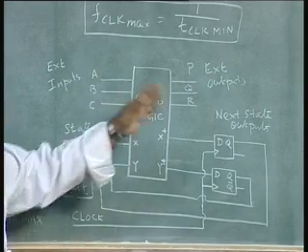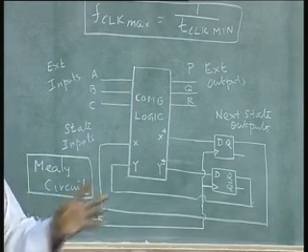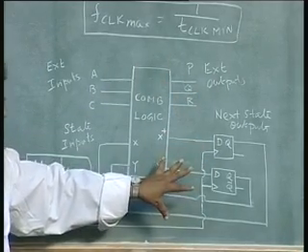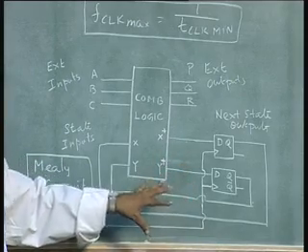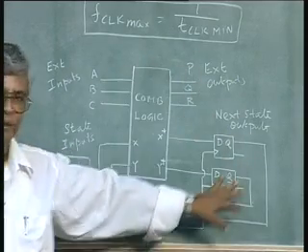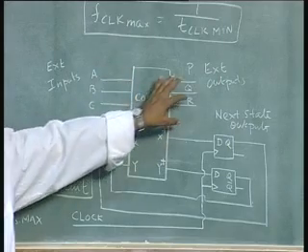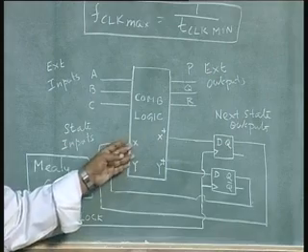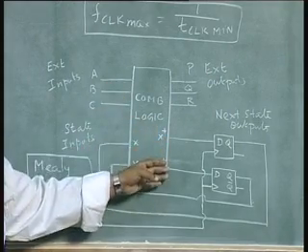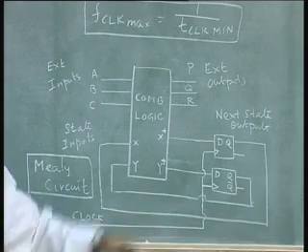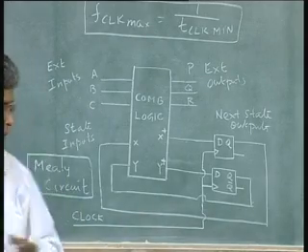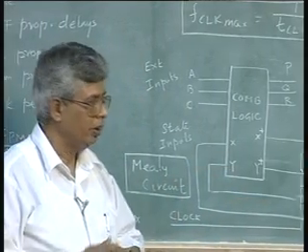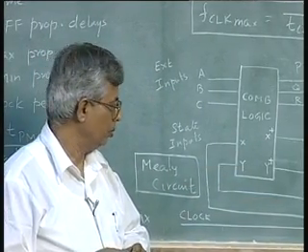But I thought I will give you these two variations, and not only that, the basic architecture. That means any digital system you are trying to design can be simplified or reduced to this format. What are the inputs, what are the outputs required externally, how many states are required, based on that state variables are defined, and the present state variables along with the inputs design the next state variable, etc. This is a standard procedure that gives a lot of design methodology, which we will adapt in the subsequent lectures in order to design different types of digital systems.